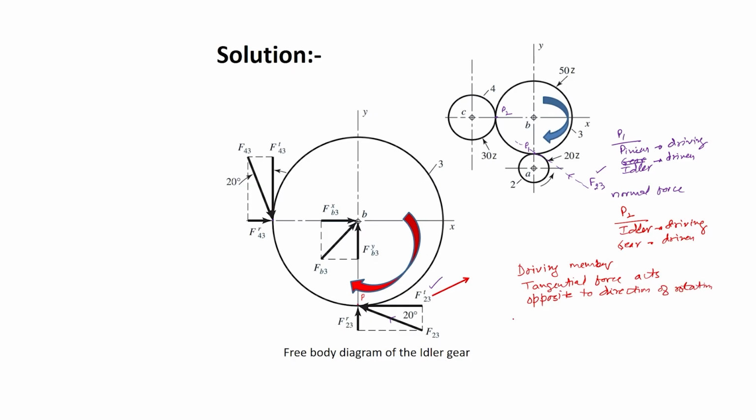For the case of the driven member, the tangential force, the force component tangent to the pitch circle, acts in the direction of rotation.